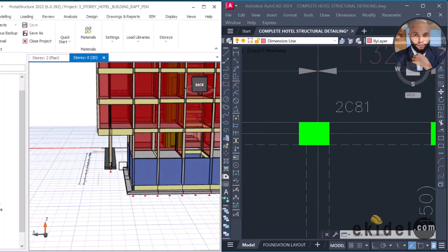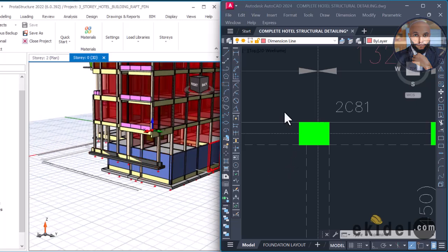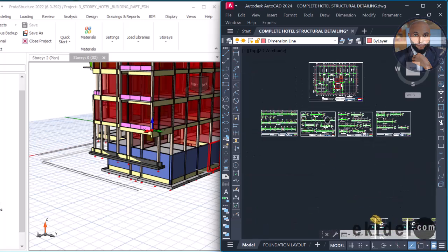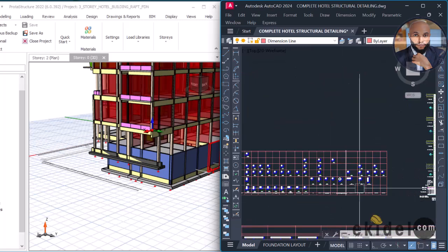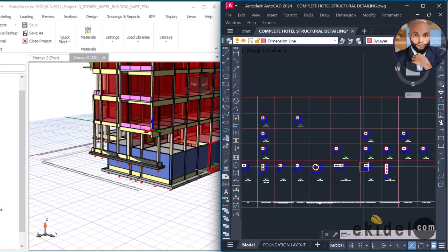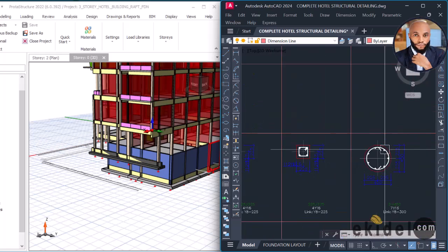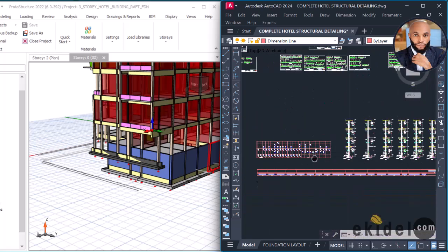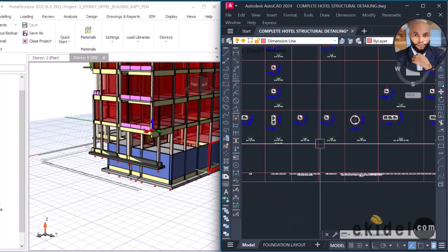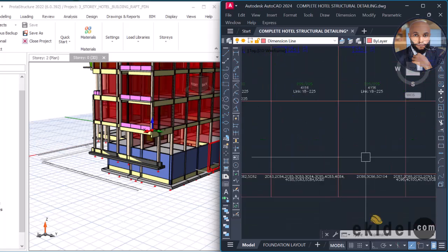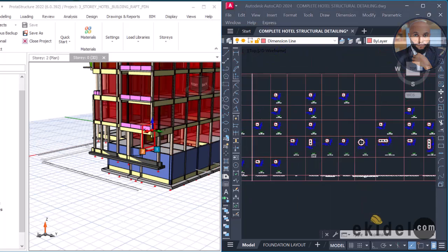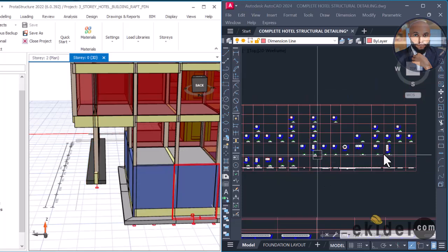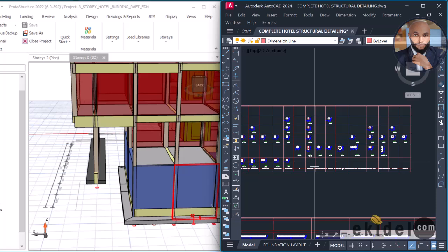Okay, so knowing all these features right now, we will go to the column schedule here, because we have already brought out the column schedule, which carries all the column reinforcement that we need. You can see that this is the column schedule. This was where we got our values that we did for the circular detailing. Okay, and then we will look at column 81, the shape of which is 300. Yes, let me check. Yes, 300, which is this at 300. So this is the column here.